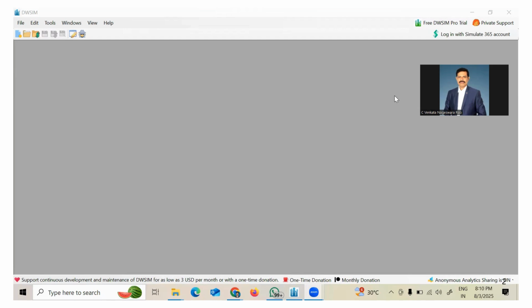Hi. In this session, we're going to learn how to generate the VLE curve, the Vapor-Liquid Equilibria curve, or to be more specific, Isothermal VLE and Isobaric VLE, as well as the equilibrium curve, that is X versus Y: the mole fraction of the more volatile component in the liquid phase versus the mole fraction of the more volatile component in the vapor phase. I am speaking with respect to binary liquid mixtures, specifically organic mixtures.